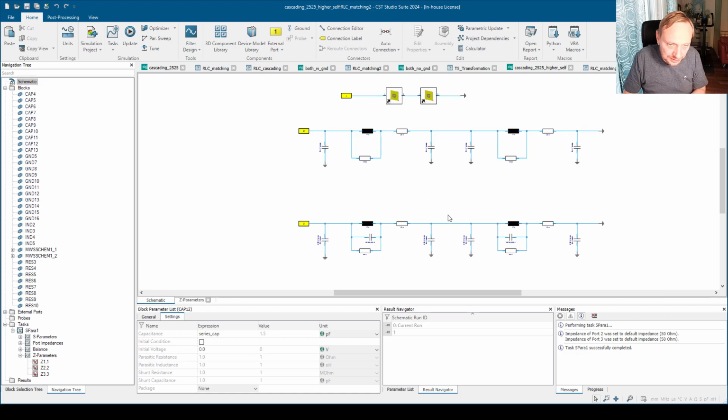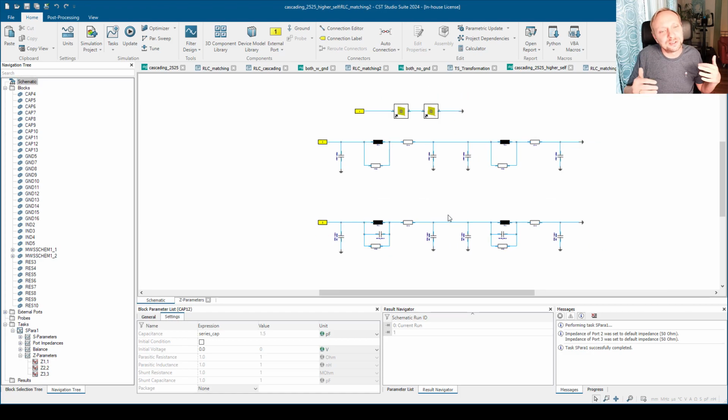And then you can see that again, the Touchstone files won't let you down. The Touchstone file and the measurement do the right thing. It's S-parameters. It's a very good, stable theory, and I'm a big fan of this theory. However, it tells you one thing. If you obtain a measured file, you always have to ask yourself, although I'm saying this in the other video, what's contained inside this file, right?